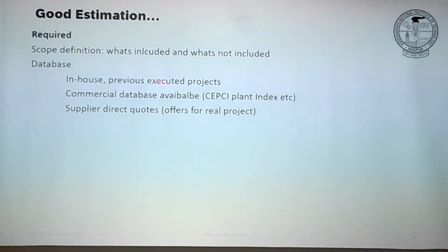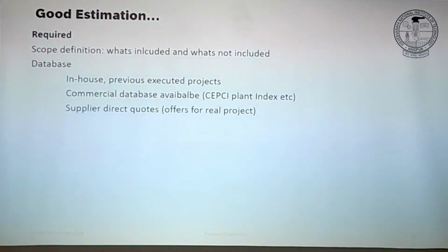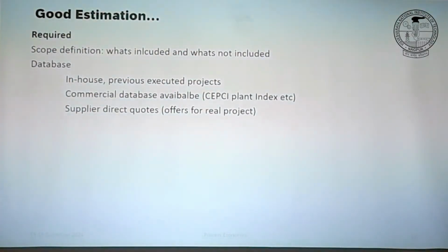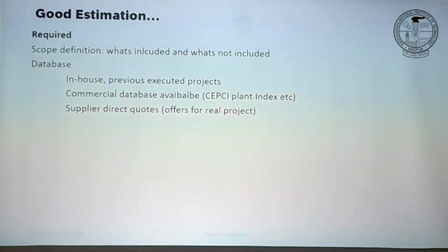In a department, they will keep all this information in a way that if they have to do estimation on one new reactor, they will take out 19 data points and simply calculate the best possible way for this new reactor. So this can also be in-house within the company, but that's only possible if you are doing this frequently. If you are doing this once in 5 years, it makes no economical sense to maintain such a database and department. Then, as I said, there are commercial databases available. You have to pay for the subscription, and then you can get all this information.